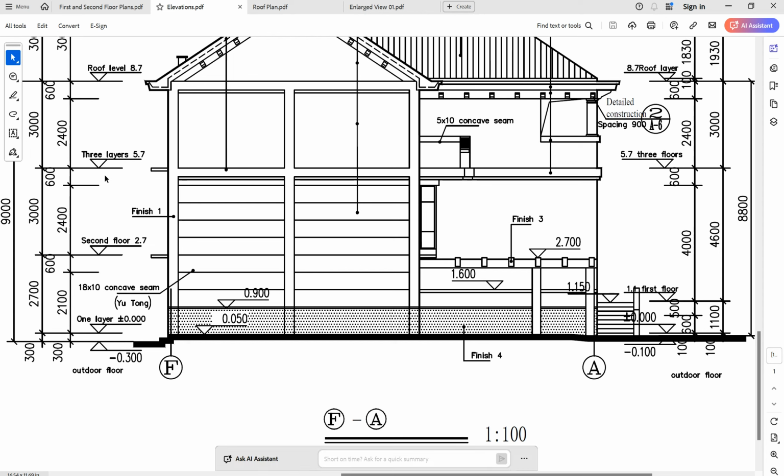But here you can see that they put that name, but I prefer third floor and roof level. Okay, so I will change the name accordingly. So this one, click here, I click one more time, third floor, and click yes. This one I can go first, and this one I will put roof level. If you want to put level plus 8.7 in brackets, click corresponding views, yes. So you can see all these things, but I haven't corrected yet the floor and roof level.